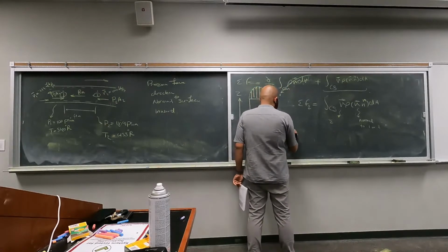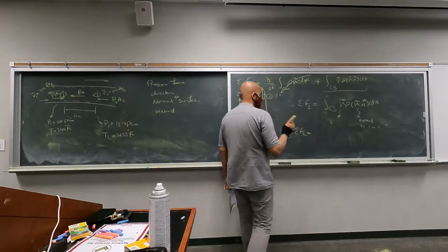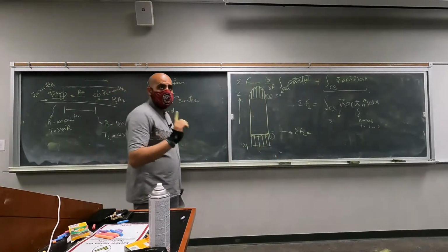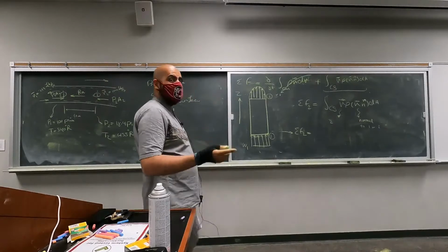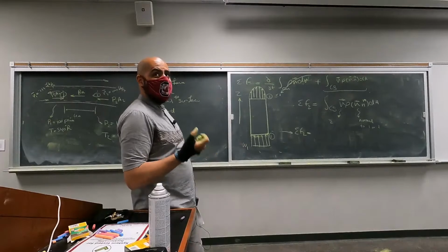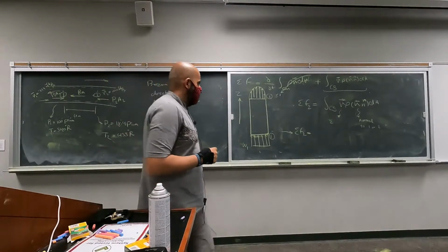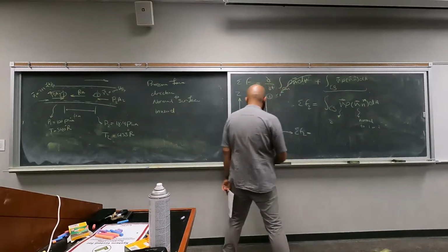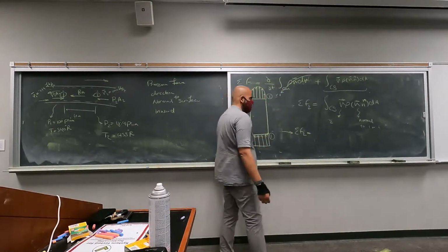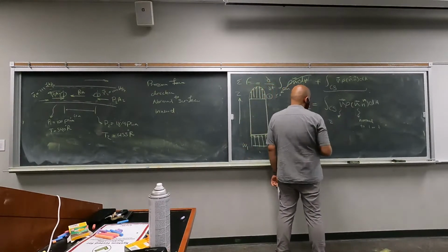So sigma F in the z direction, because again, we want to find the pressure drop, right? So we have to calculate the net pressure force and include all of the other forces, and from there calculate the pressure drop inside this pipe. For the inlet area, we have uniform velocity. We can take it out of the integral. Density is also constant. Take it out of the integral.